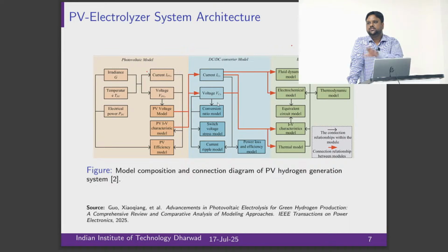So you need a step up operation. The basic structure is a single stage boost converter, and you can achieve the voltage from the solar input, with the output being the grid level inverter DC link voltage. Okay.